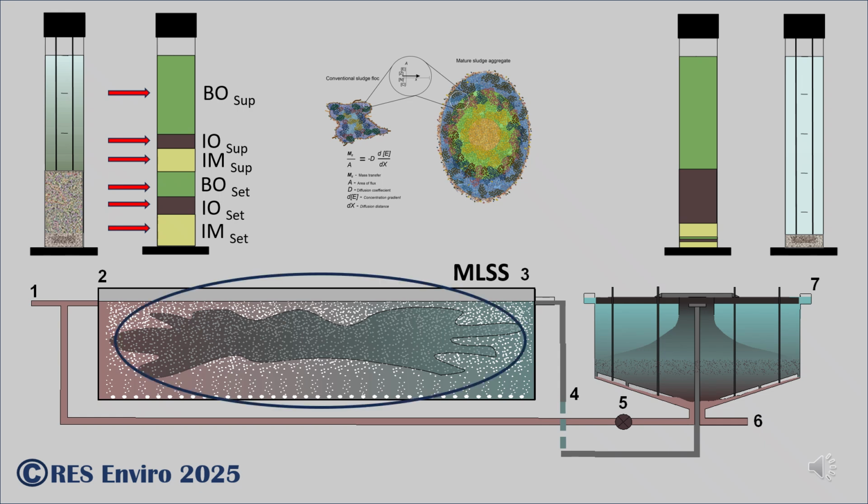The mixed liquor in the reactor is a mixture of bioculture floc, complexed and infused by the mass of pollutant solids that are continuously mixed into the reactor. The mass transfer of the solids in the mixed-in wastewater to the bioculture floc in the reactor describes the filtering action of the reactor as its method of pollutant removal.